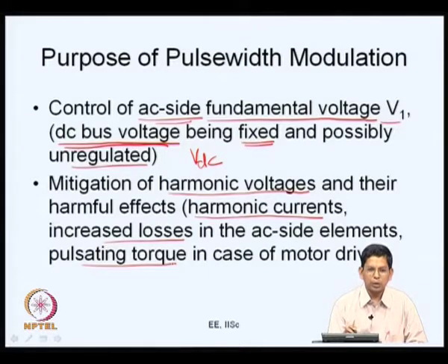And if you look at them through phasors, we will deal with all this at a later date in greater detail, but just to help you grasp this, you have two fields, one pertaining to the stator and another pertaining to the rotor, which both revolve at the same frequency and they have a fixed phase angle. Because of the interaction between the two, you produce a steady torque.